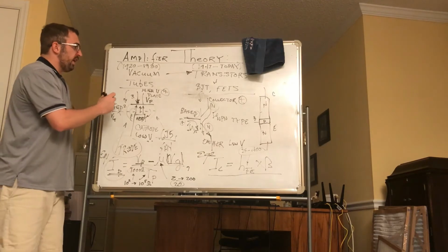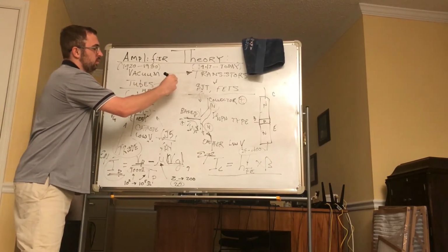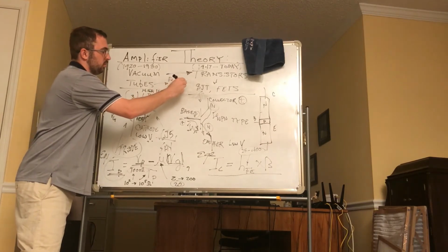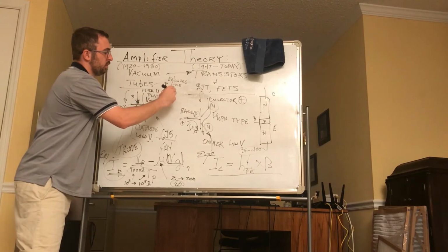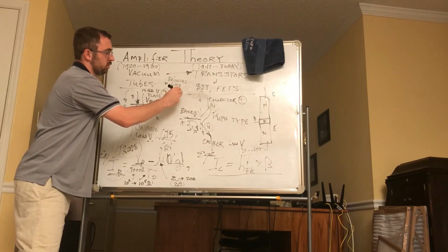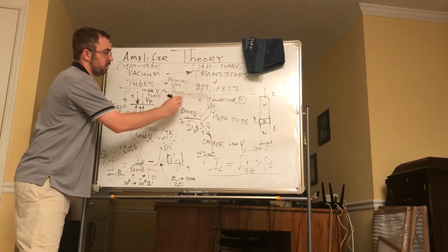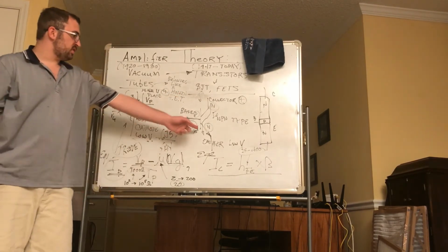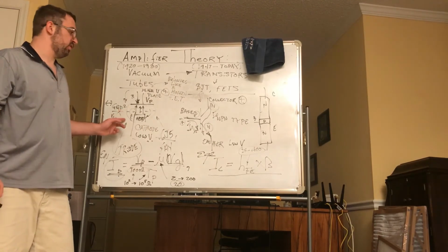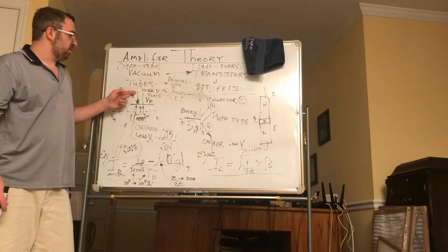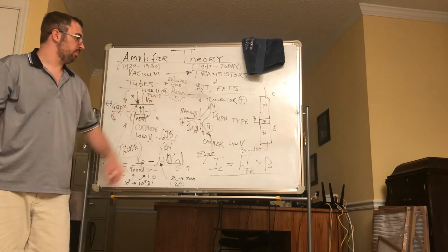So a vacuum tube actually behaves very similar, behaves like a modern field effect transistor. A rough comparison, these guys are good at controlling currents, these guys are good at controlling voltages, very large voltages. Typically you'd have 100 volts or more here, 100 volts or more here would destroy him.